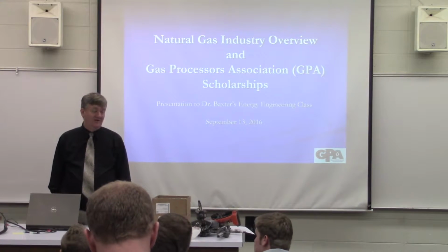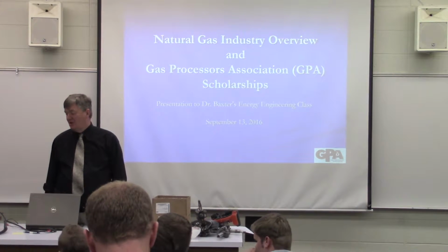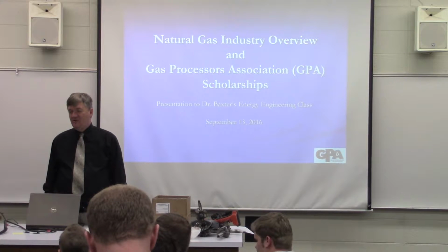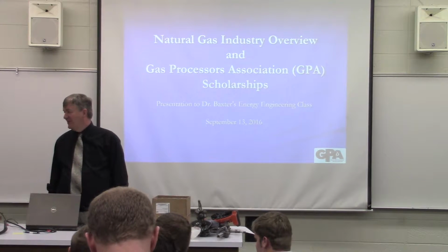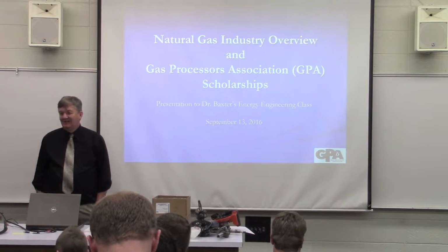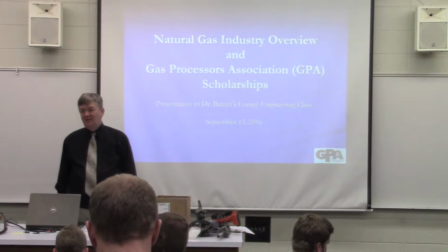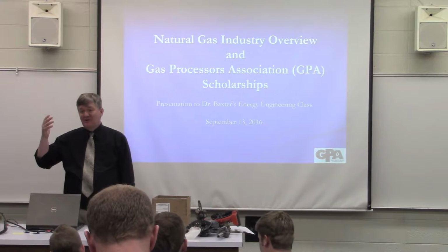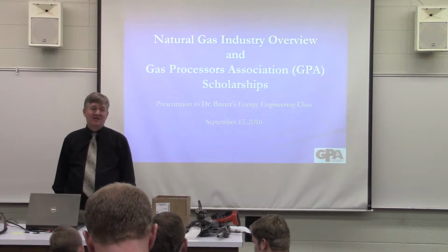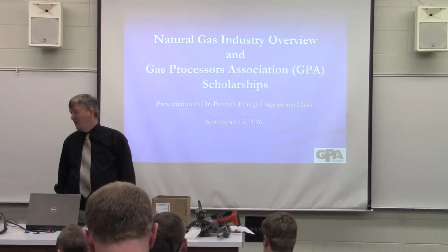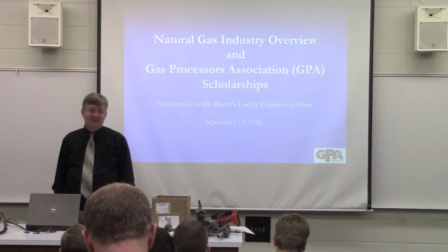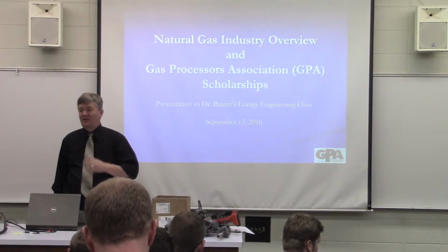CO2 and ethane form an azeotrope, and that's the largest application of azeotropic distillation in the world. Oil refinery, that first column that we talked about, is the largest use of distillation, but it's followed by the first step in natural gas processing, which is demethanation, so separating the methane from everything else.